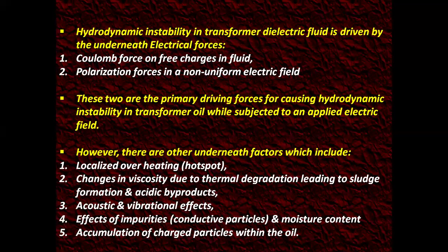Hydrodynamic instability in transformer dielectric fluid is driven by the underneath electrical forces. Number 1. Coulomb force on free charges in fluid. Number 2. Polarization forces in a non-uniform electric field. These two are the primary driving forces for causing hydrodynamic instability in transformer oil while subjected to an applied electric field.